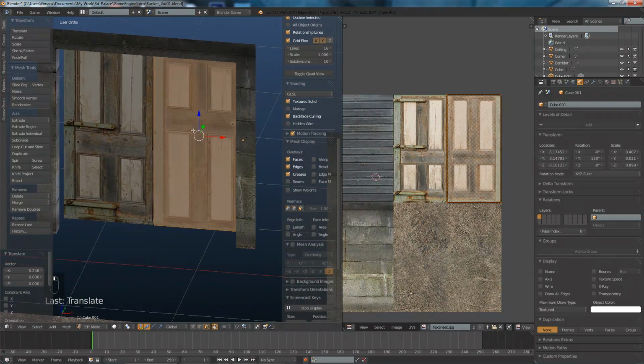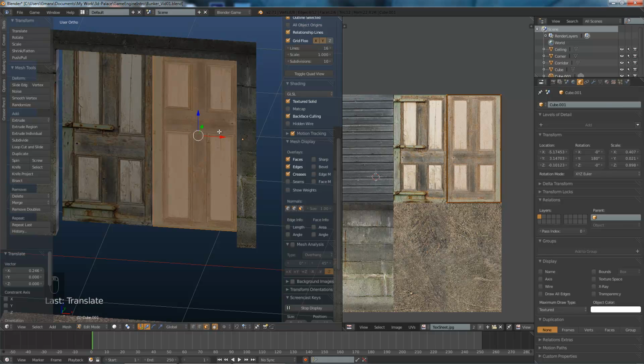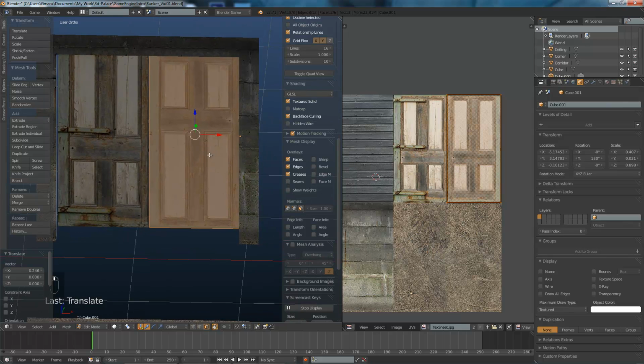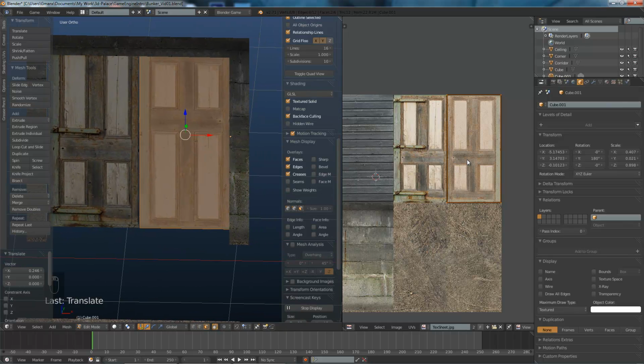Because we've turned it around, we're actually looking at it upside down, so I might scale these in -1 so that that green bar is at this side of the door, so it matches the other door better. So with our cursor in this UV area, we'll hit S, X, -1, enter.